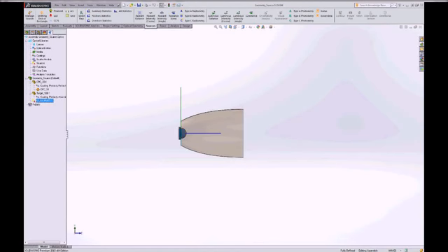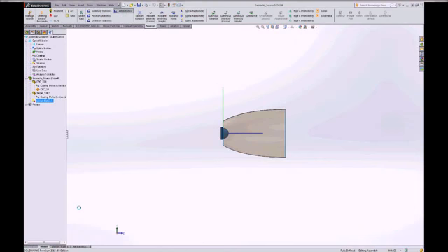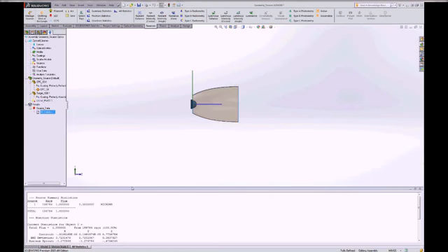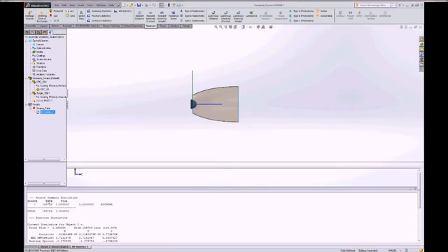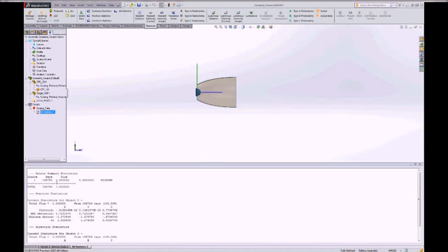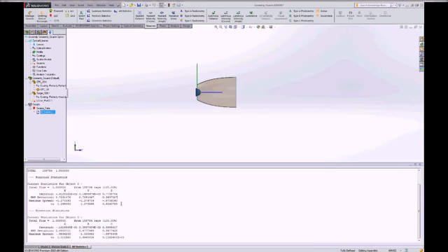So I've selected the source icon here within the Optics Manager, and we can look at some statistical data. In this particular case, we see how many rays were actually generated, a little more than I asked for, but I do have my 1 unit of power at the default 0.55 micron wavelength. And I can also get information about the positional distribution, and I can also get information about the directional distribution.